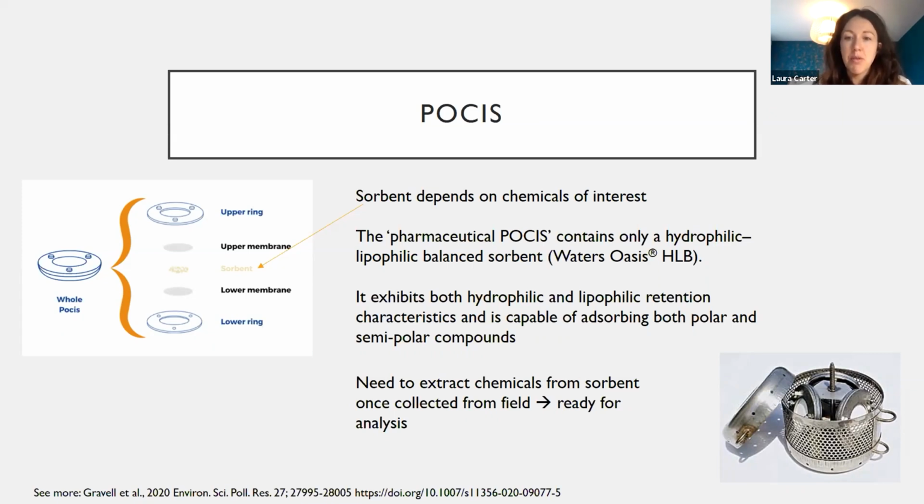So at the moment, this all sounds great. But if you're going to use these quantitatively, then they require quite some effort to calibrate. You need compound-specific uptake and diffusion coefficients, which require quite a lot of work to generate, and they can be determined both in situ as well as in the lab. You also have to deal with potential losses of the resin or sorbent. Even though they're encased within this system, sometimes you can lose the resin, and then you need to account for that when you're doing your quantitative calculations.